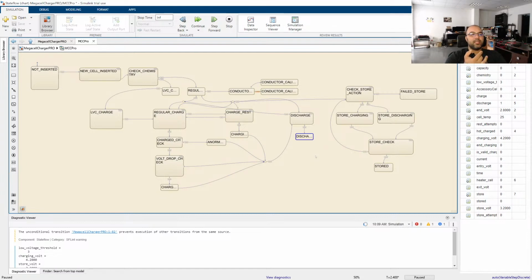So now the last thing that I've added is the PWM per cell for discharging, so I will be able to implement constant current and constant voltage when discharging, and also I have access now to every charging IC to set the charging rate and charging voltage, charging current and charging voltage. So we'll support different chemistries for all different cells and all that.